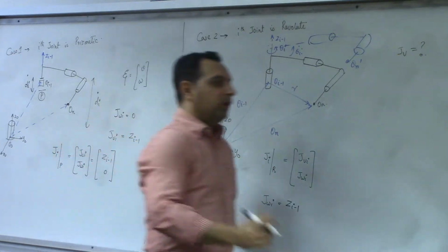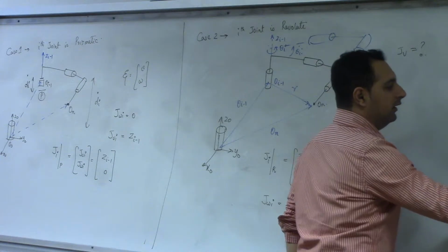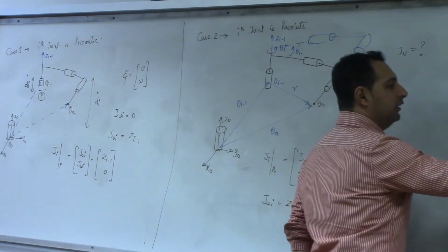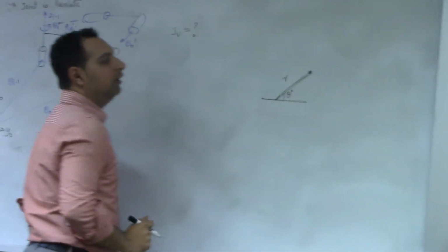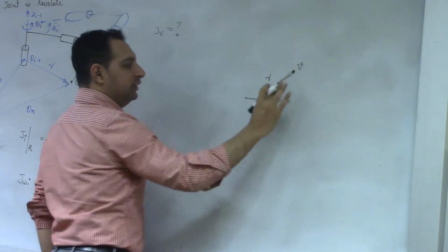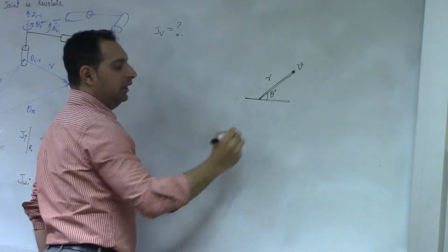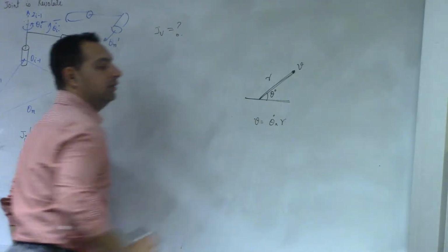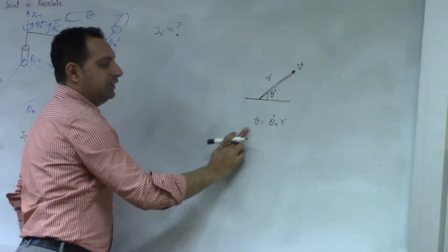Okay. So one thing that you should know is when you have, let's say, a joint like this, this is the length of the joint. And if you're tracking the point here, and if this is turning at a rate of theta dot, there is a relation between linear velocity and the angular velocity. So V will be equal to theta dot times R. Okay, omega R. So the longer R is, the faster it will have.